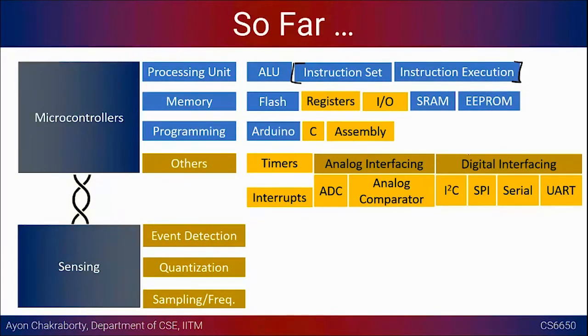with those, they understand this digital data. It's not an analog device, and you have to come up with some protocols in order to talk between the microcontroller and those sensors. So for that, we have these different types of protocols under this digital interfacing category: the serial interface, the universal asynchronous receive transmit, SPI, I2C, and so on.